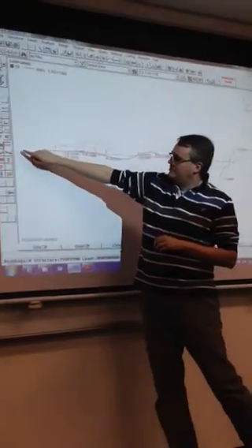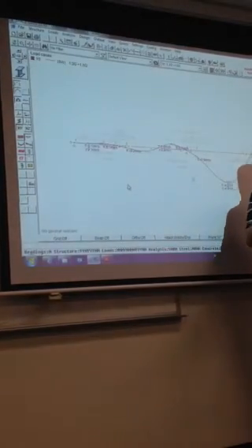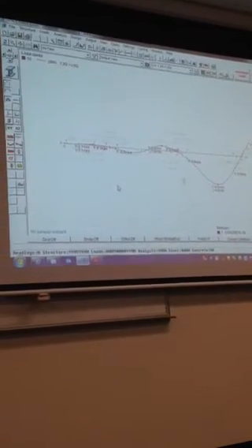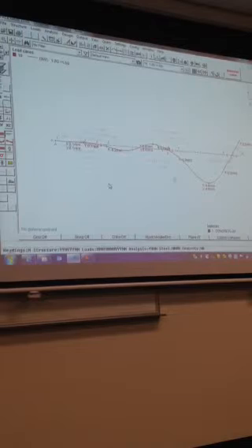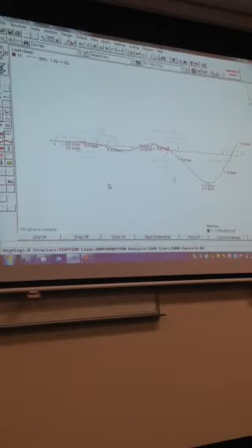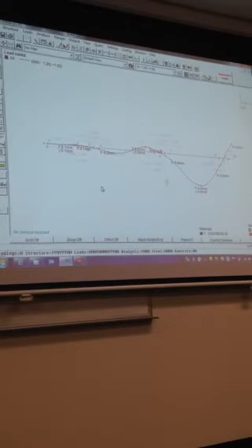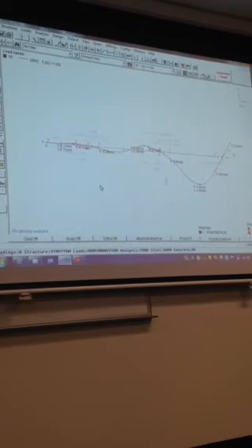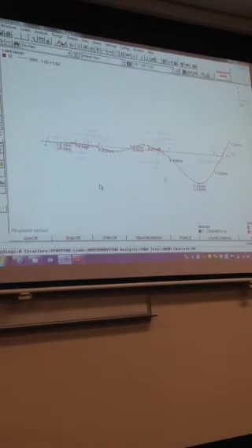But don't worry about that, I'm just showing you, so you can use this little deflected shape icon over here. If you're not sure which ones they are, just move the mouse over it and it gives you a description of what that button does. All right? So that's what you guys need to move on to next with your one-way slab. The design we won't go through, but that's the analysis. And next week we'll go through the concrete beam as well. That's a little bit more complicated, but along the same lines. So we've got to look at the geometry, set up the proportions, and then go from there.